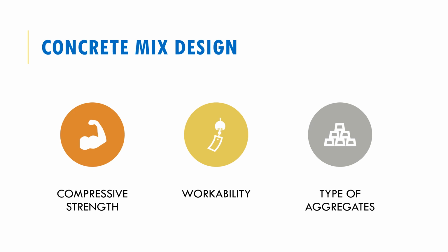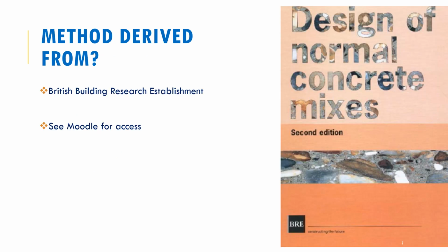Now, in terms of the concrete mix design itself, some of the factors that we need to consider: compressive strength, of course, the workability of the concrete, and then the type of aggregates. And these are basically considerations that are outlined in this BRE guideline, so the British Building Research Establishment. And it lists down the different stages that need to be followed when you want to produce a certain design of your normal concrete mix.